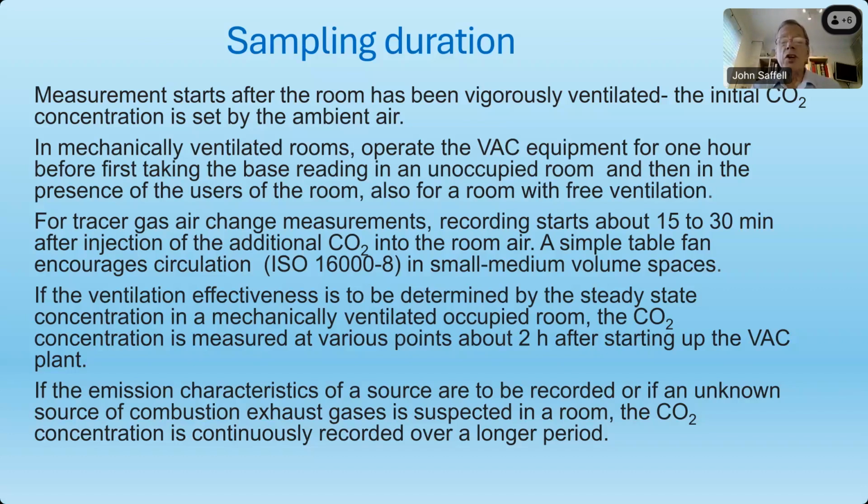If it's to be determined by the steady state concentration in a mechanically ventilated occupied room, then it's measured at various points after about 2 hours after starting up the HVAC plant. So it takes about 2 hours from the time that you have a baseline until you have something that you're hoping is steady state, if you're going to make a steady state measurement. It's quite a long time, but that's how long it takes spaces to stabilize.